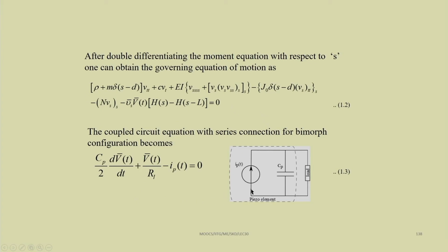Now for the circuit, we can draw the circuit diagram, and for the piezoelectric patch we can write the equation of motion. This equation is Cp by 2 dVt by dt plus Vt by R minus Ipt equal to 0.